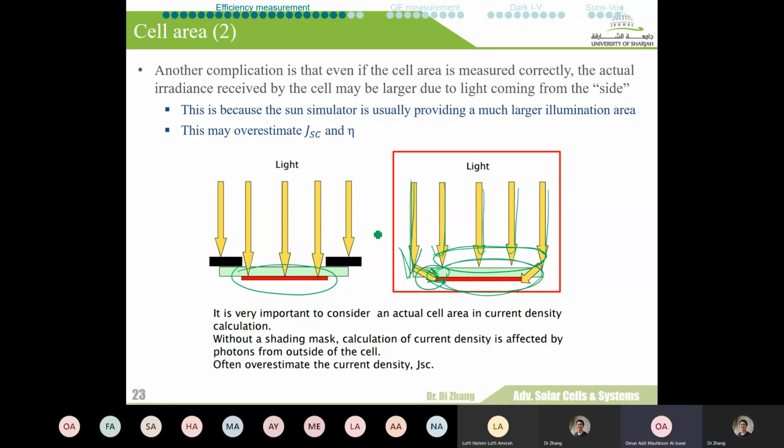I think another issue is that we can get light illumination from the lamp itself as 1000 watt per meter square, but the incident light is not 1000 watt per meter square. For example, I've noticed in the solar PV lab when we were doing the experiments, even though we have the lamp just above the solar cell, and we put it horizontally, sometimes the lamp itself is tilted. So we are not getting accurately 1000 watt per meter square. So I think we need a measurement sensor to make sure that the incident irradiance is 1000 watt per meter square. Am I correct or not? Yeah, that's correct.